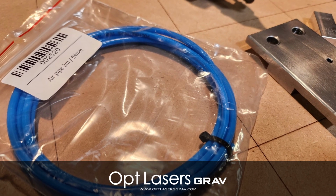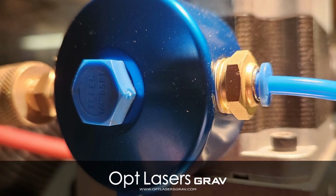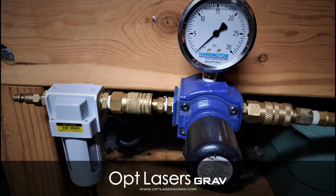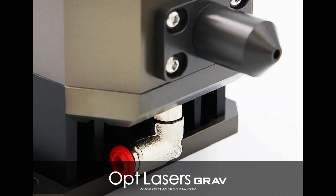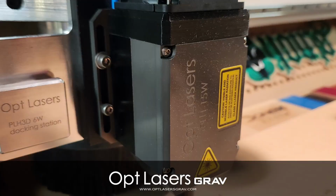If your laser has air assist, you'll need to locate the 4mm air supply line. An air manifold, push-on connectors, pressure regulator, and water separator will help with this setup. Attach the air line to each laser using the push-on connector. This completes the installation of this laser.